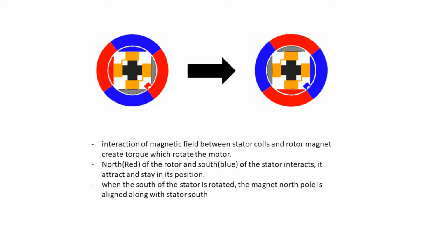A brushless DC motor is essentially flipped inside out, eliminating the need for brushes to feed the electromagnetic field. In a brushless DC motor, the permanent magnets are on the rotor, and the electromagnets are on the stator. A computer then charges the electromagnets in the stator to rotate the rotor a full